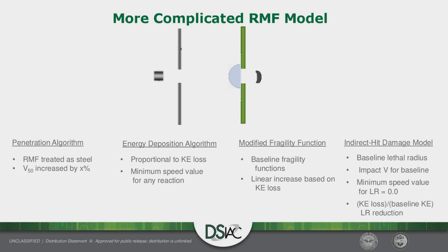A more complicated model: I don't want to take this too far, but I did add some complications to it. I just decided to treat the reactive metal fragments as steel, using the penetration equations for steel, but increasing the ballistic limit by a percentage that the user can control. The energy deposition algorithm just assumes that the energy deposited is linearly proportional to the kinetic energy loss in the projectile.